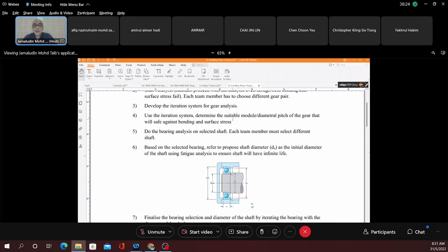You have to do a bit of adjustment here. I advise you to keep it very short, for example, between the bearings maybe 50 millimeters, don't try 150 and so on. You can use all the dimensions from the shaft, for example the radius of the fillets and so on here. This is going to be your initial bearing. You get this after you do the bearing analysis.